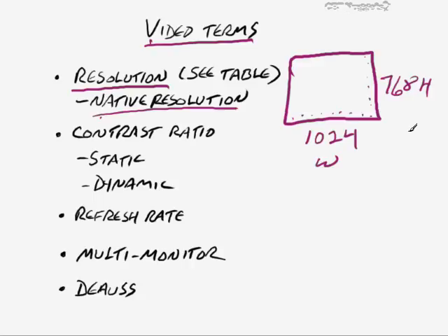Key things to keep in mind with that is, number one, you can potentially damage your display, especially on a CRT, if you go out of scope for whatever it's specified to be able to handle. And the same would be true if you adjusted the refresh rate, especially on a CRT, to be higher than it's designed to be able to handle as well. You can just totally ruin that monitor. So be very, very careful of that.